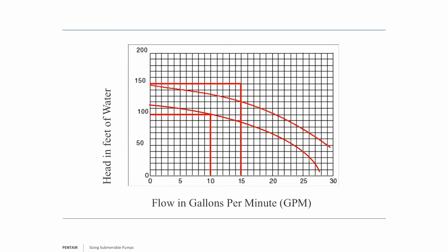It's done. Now, granted, in this case, if we could pull the pump and take the B and A out, maybe put in different C's or whatever to change that head, yes, you can do so, but that's labor intensive also. That's why a lot of people are opting for variable frequency drives and using the original curve, but changing the RPM of the motor to meet the need.